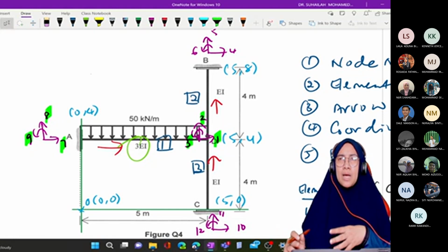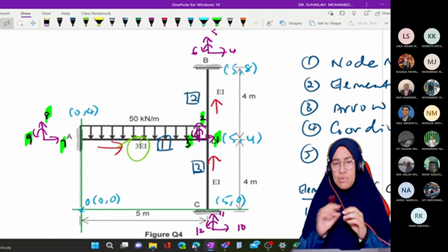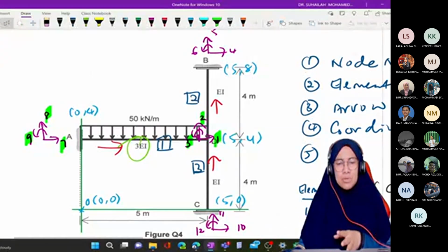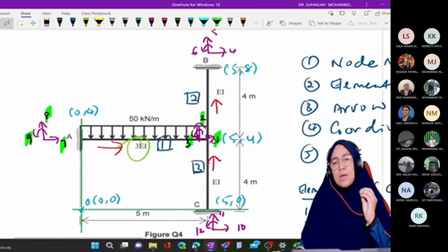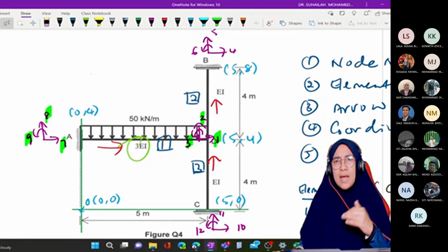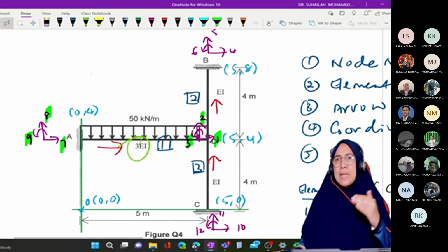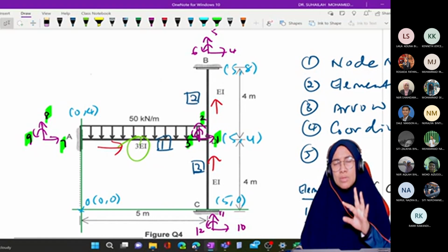Okay, to node A and node B, node D. Node A and node D, we have to distribute it. For element number 2 and element number 3, since there is no horizontal force or UDL subjected directly along the member or on the member, maybe at the center there is no force. So Q2 naught, Q3 naught, all values will be 0.